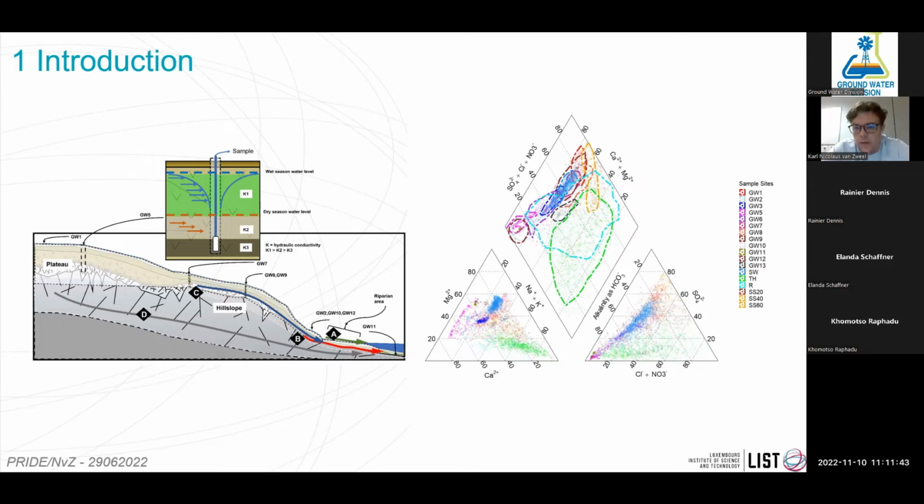So if we look at the Piper diagram, you can already see there are some interesting trends. This light green color is throughfall, because the catchment is covered by a mixture of vegetation, spruce and Douglas fir. This vegetation has an influence on what is input in terms of chemistry, but we also monitor dust deposition, and obviously the pure rainfall as well. The pure rainfall is the blue cluster, and then this light brown color is the soil water composition, and the clusters that you see here are all groundwater clusters.